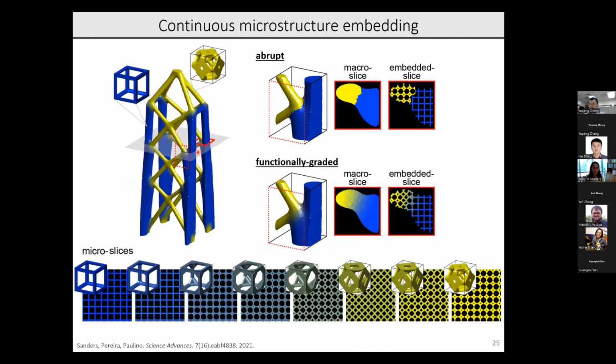So our optimization-based design approach gives us essentially a density field that's a mapping between location in our design domain and the meso-architectures of interest. Could be these main 2 meso-architectures or an interpolation between them that enables us to achieve functionally graded transitions. But essentially the idea is we're doing a Boolean intersection of the volumetric topology optimization data and tessellations of our architectures over the design domain.